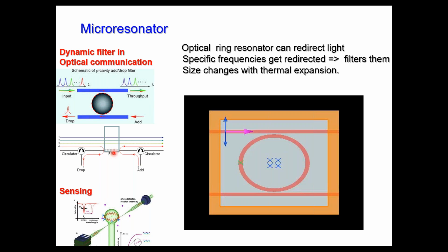Because there is an FBG, its periodicity is adjusted in such a way that it acts as a filter for only one wavelength. The circulator is a unidirectional, three-port device: whatever input you give exits through the very next port.